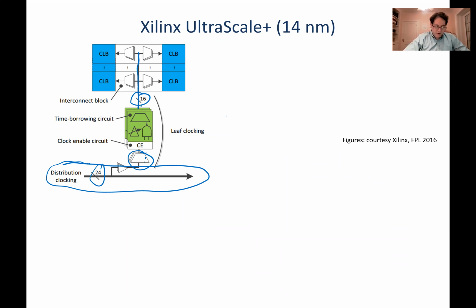So they pick whatever clocks you needed from the pool of clocks that are flying by, and this is their last rib, basically. This is what gets you to a fraction of a column, so maybe 1/8 of a column in the chip. And all the logic blocks on either side of that column can pick one of those 16 clocks. They have some muxes to listen to that.